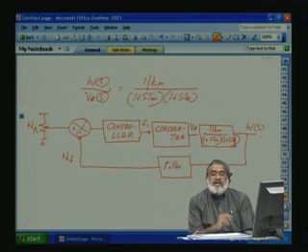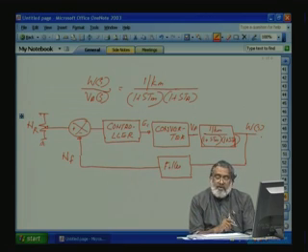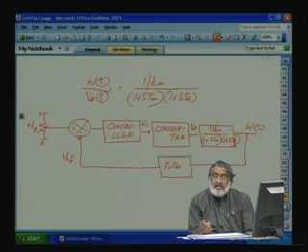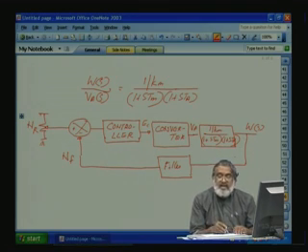So any speed change, any speed control also has to have a current control to take care of the motor. So that part we have not put here. So from the converter and controller, before going to the machine, there should be a current control loop. What does that mean? The Va applied voltage to the machine now is not dependent on the speed error.